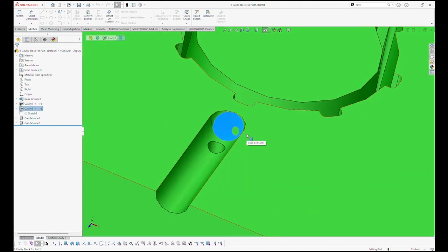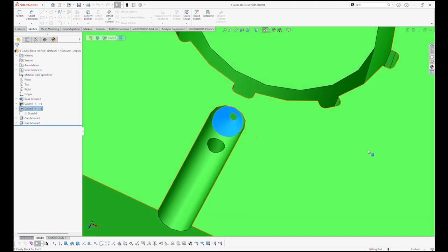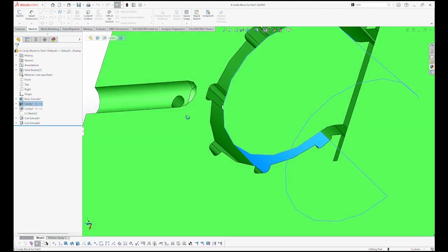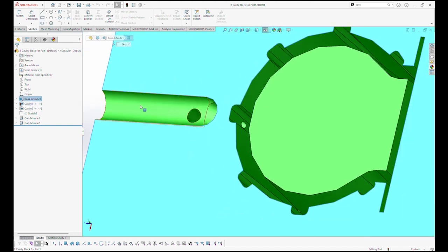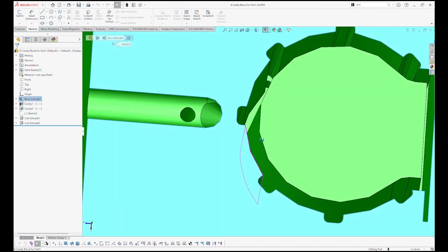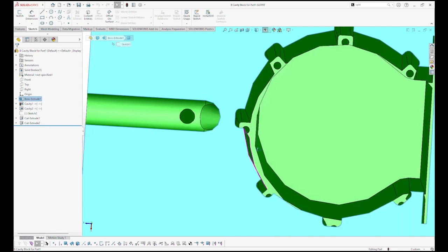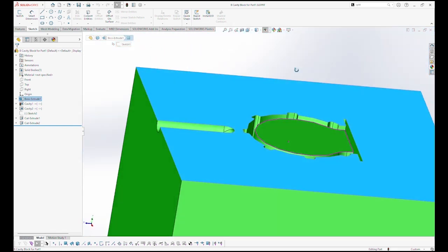And so you can see that cone there, and then you click on this surface here and you see that hole turn blue because it's showing that surface. And you can see that the gate is literally an opening in the cavity block that allows the molten resin to come into the cavity shape, and the cavity shape is that 3D solid model that we had created.